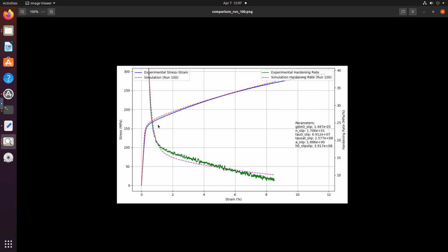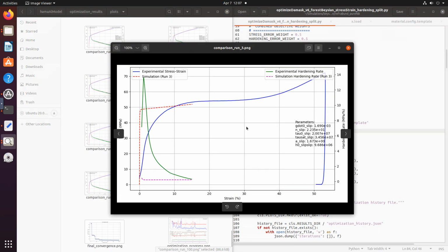from there it finds a very nice parameter space with minimum error, and from here you can choose which curve match you like most, and pick up that material file with that set of parameters and use it for all your next simulations. Make sense? This is what we are aiming for, this is what that script is written for, but you can modify that and play with it for your own case. I had to clean that data and run simulations up to a similar amount of strain to get a good fit and comparison. That is what I want you to do here.